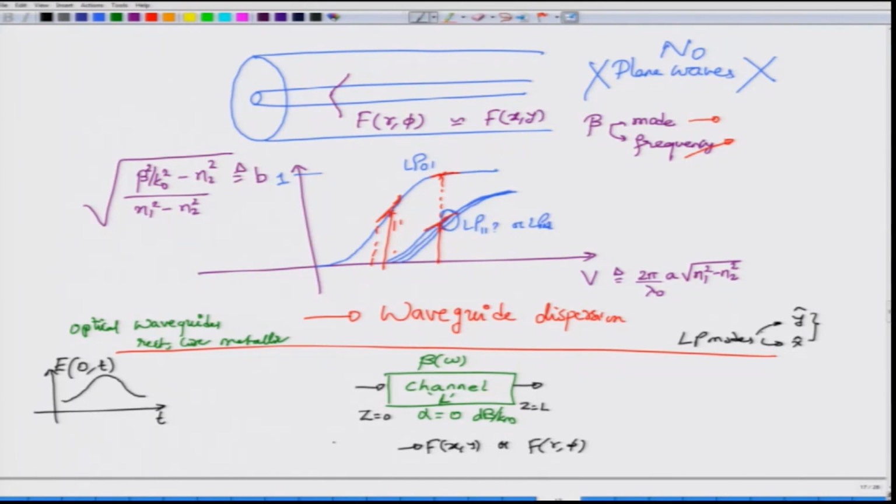Of course, when you have multimode propagation, this assumption is not true, but what we will assume is that once you have a certain set of modes, for example LP11 and LP01, you will also have an LP02 mode. The mode shape here would by and large be independent. This is the LP11 mode. So, you will have an LP02 mode. This shape would not depend on frequency. That is a reasonable assumption to make. So, the shape remains the same as the pulse propagates.